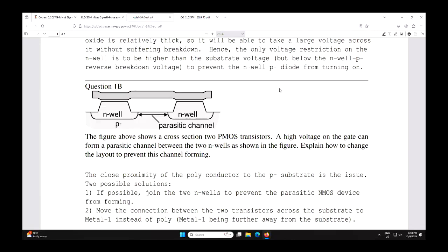It's hopefully there, but maybe it wasn't enough, because maybe in this situation you're doing a high voltage circuit, maybe you're having 1.8 volt transistors everywhere, but these sit in the floating well, so maybe this sits 20 volt across that, and that's what the problem is. So, yeah, there's not something you can put in as an extra thing in the layout.